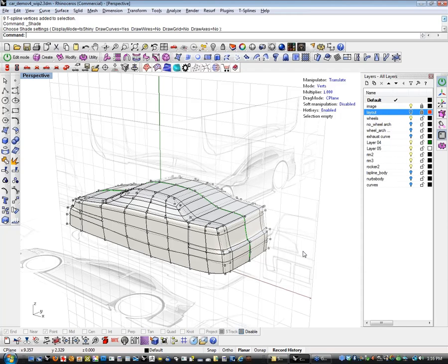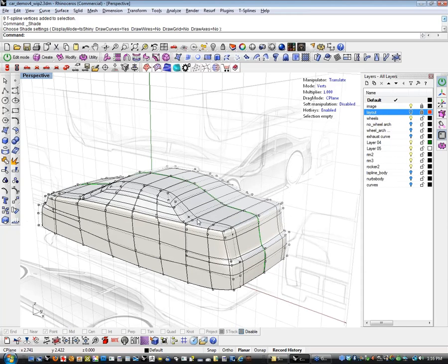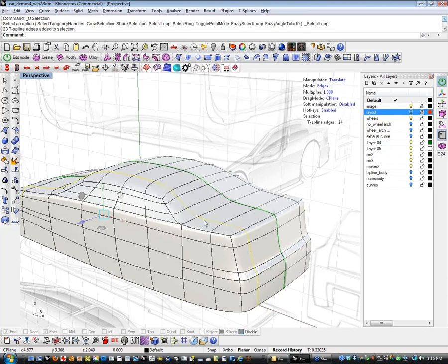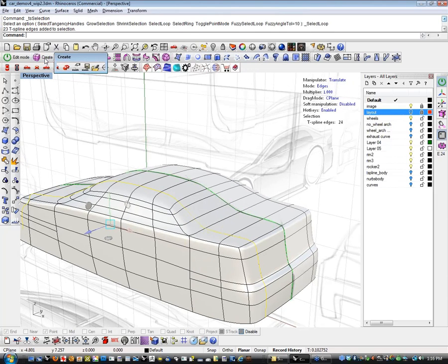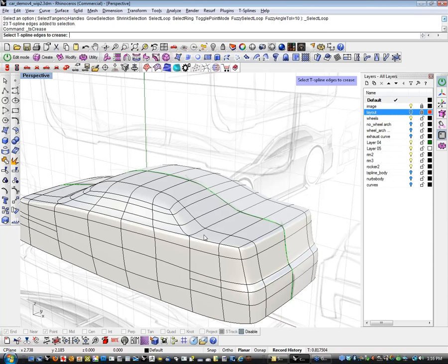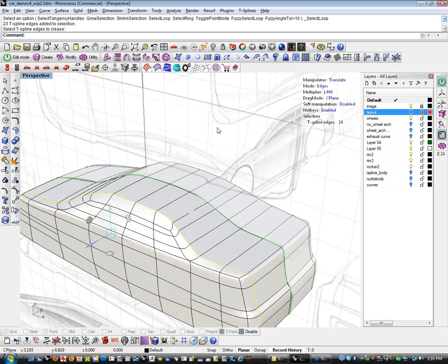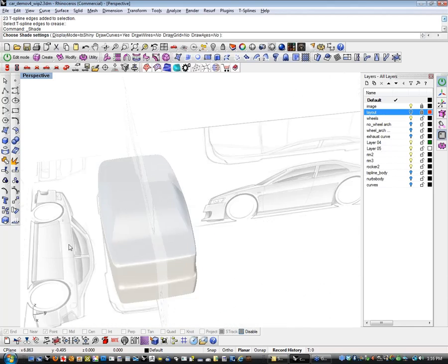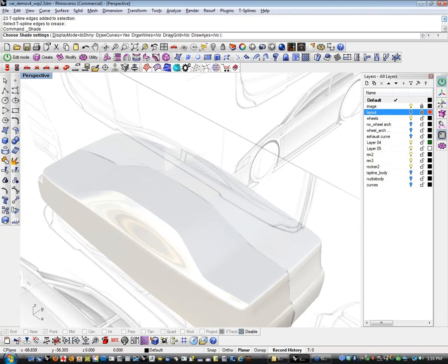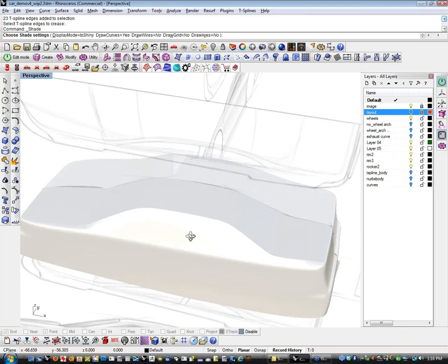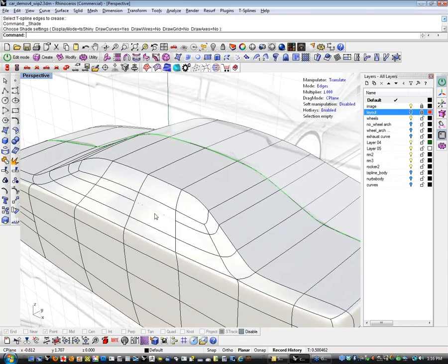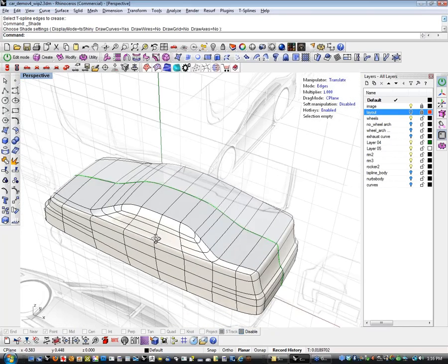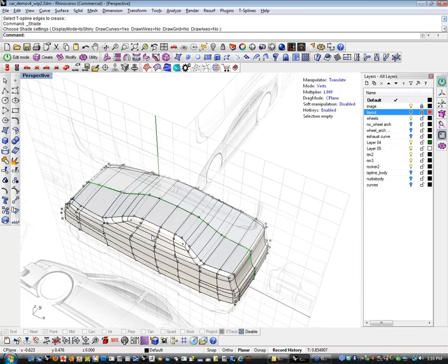Show again how to remove the creases after bringing the sides together to create the body. Let me answer that by throwing a crease on it. If I crease this, you'll notice that all sorts of really ugly stuff happens through this thing. Well, actually, it's not that ugly because it was so expertly laid out. But if you want to get rid of a crease, basically what you need to do is turn on the points.